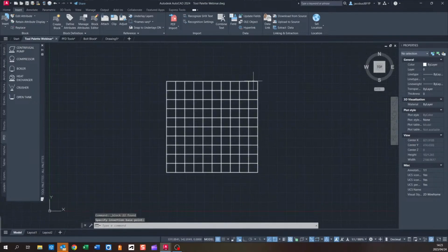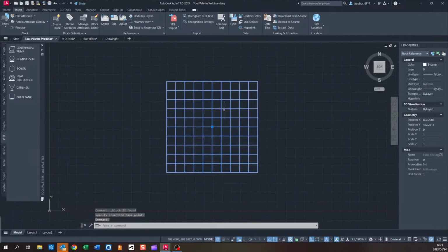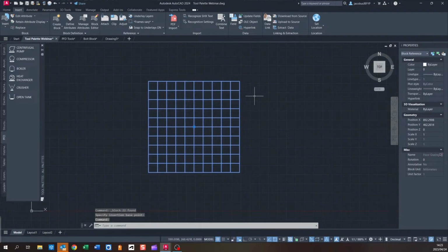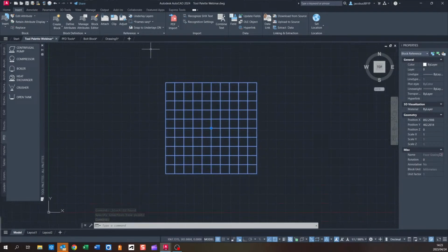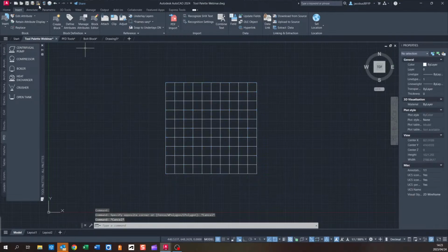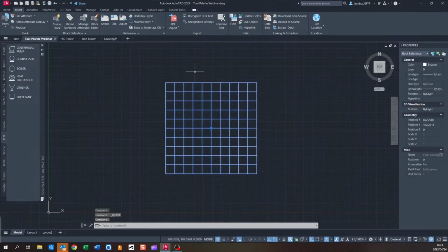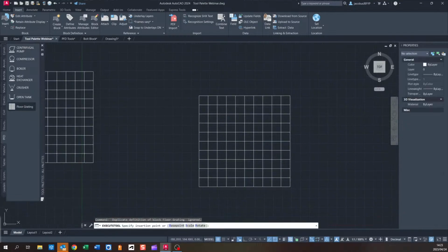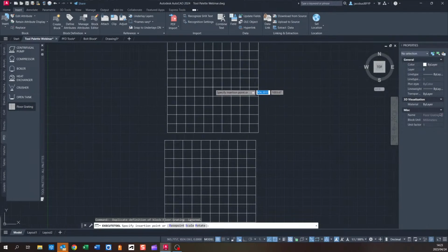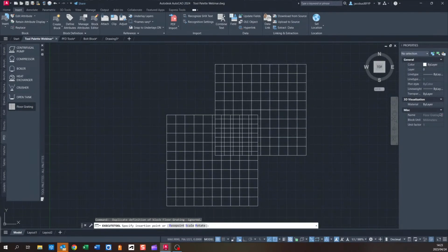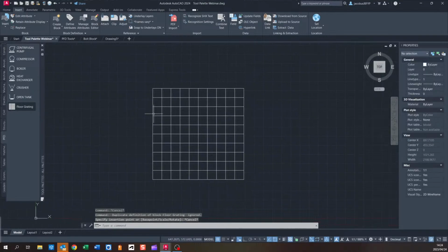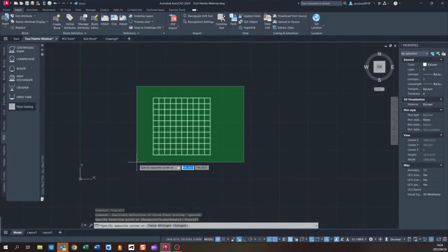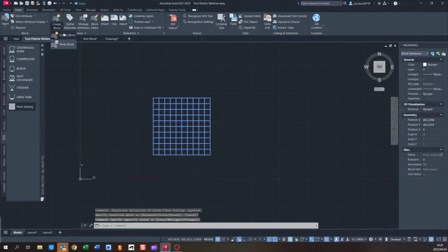And now you'll see when I click on any part of this entity, it selects the entire entity. So now, just as before, I need to save, click on the block, Control C, Control V, and there is your floor grating. So I think what would be easier is if you set the insertion point to another part of it, so let's just see if I can redefine.